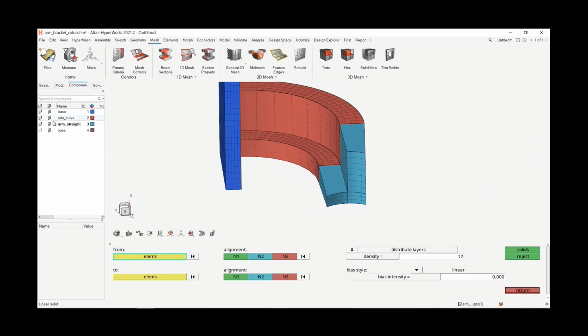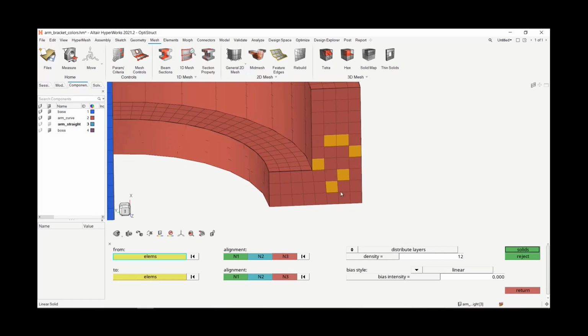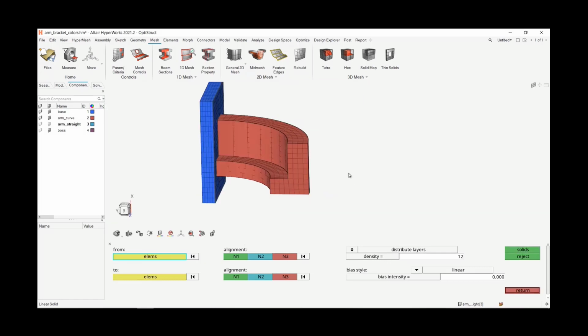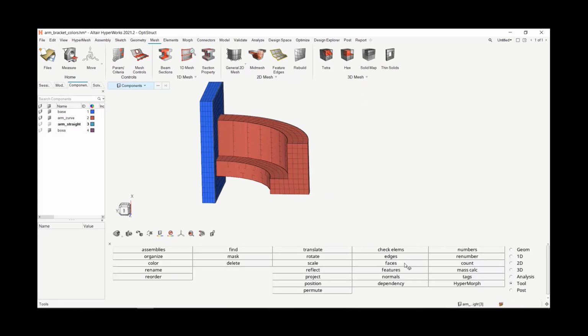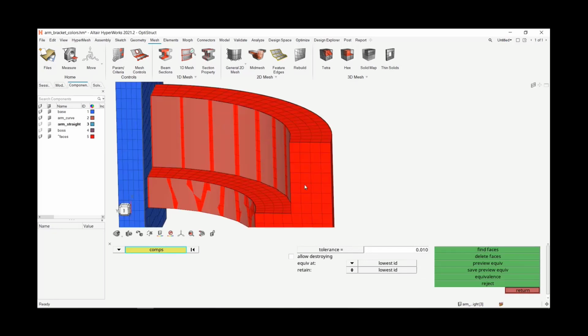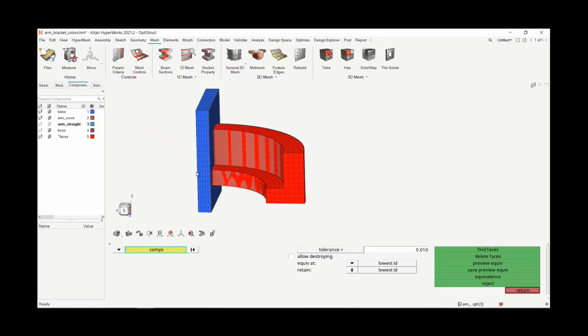All right, one thing you'll notice if I try and just go do this as is, is that I cannot select these 3D elements. Actually, I can select them, but what I usually do is go and create a 2D face here. If I select this component, say find faces, I get a 2D face. You'll notice this caret, meaning it's not something that's going to be exported. It's more just a temporary component to work with.